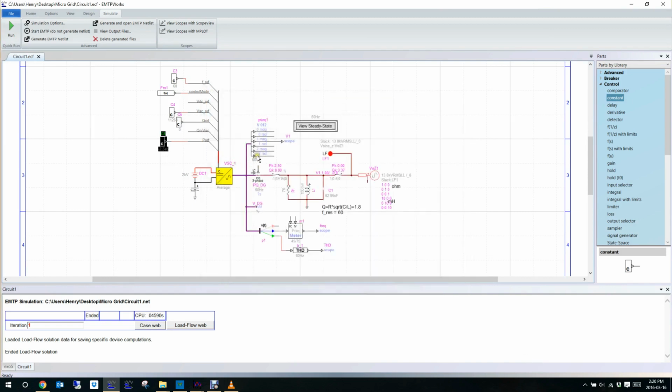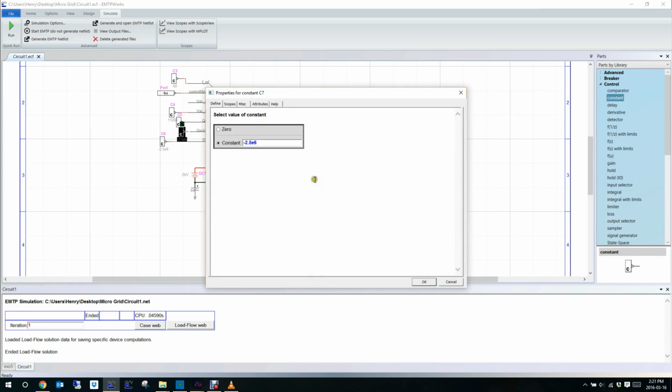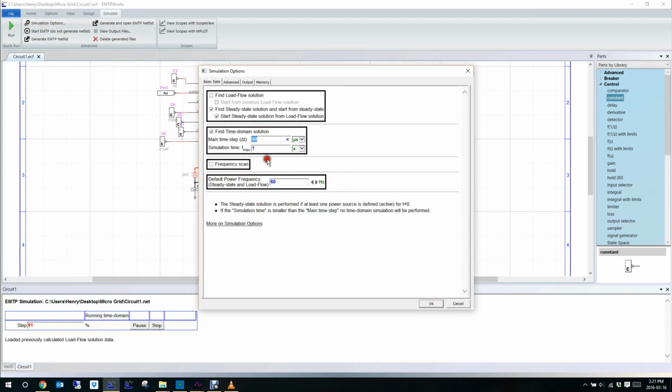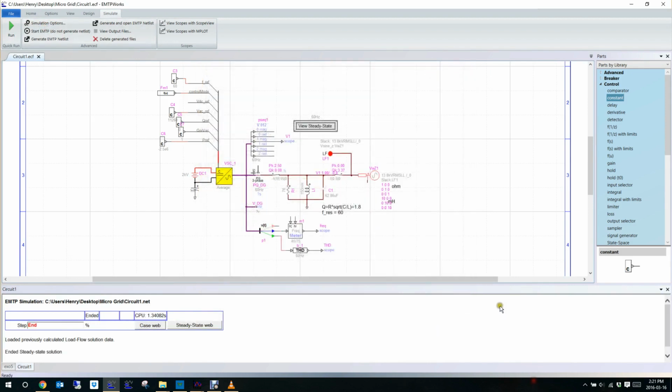And here, when we are in control mode 1, we can select if we control Q, the reactive power, or the voltage. So far we were controlling the reactive power in that mode, so we put 1. Okay, so we are good to go. Let's simulate that. Actually, let's lower the time step to 10 microseconds, because after we want to compare with the detailed value model, and the detailed value model requires a small time step. Okay, so let's simulate that and look at the scope.